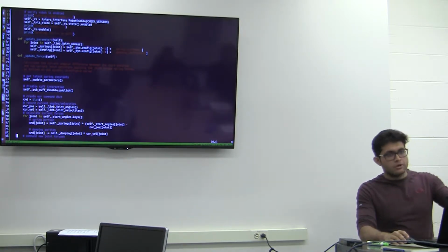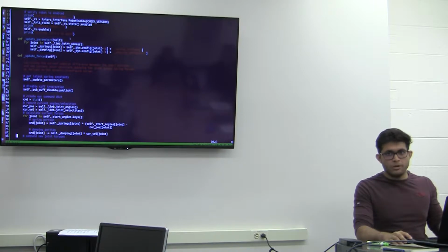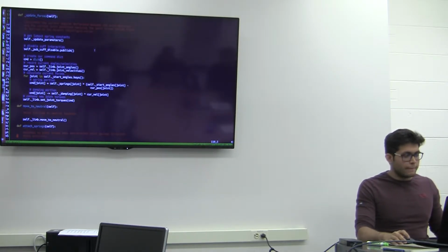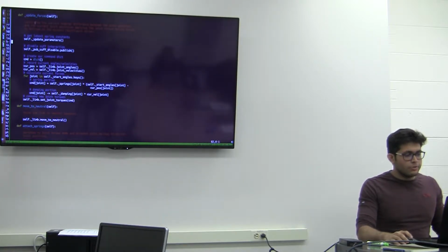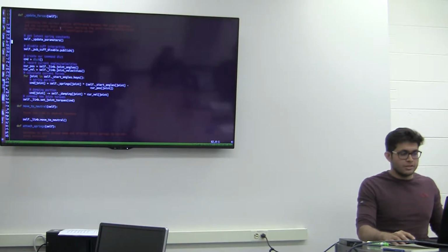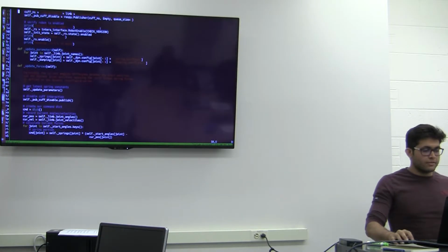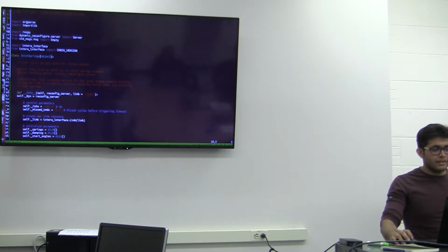Update parameters, I just call that part to update because I don't want to update anything else. It's just my gripper part, like sensor values. So now when you do forces, it calculates the current angular differences between start position and current joint position, applying the joint torque split forces as defined in the dynamic reconfiguration server. So you saw the dynamic reconfiguration server that we call here.